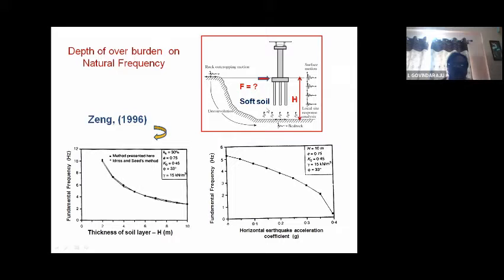It means overburden now. Sometimes you may get shallow depth, you may find bedrock, a hard stratum, a competent stratum as we say in geotechnical engineering, at very shallow depth, probably 2 meter, 4 meter, 5 meter. In some situations, you may go even beyond 30 meter. You may not get a competent strata like dense soil, but a soft soil. Now, what is the order of damage that is involved? Definitely, it is directly proportional to the depth of overburden, from the bedrock to the ground surface. So the fundamental frequency of the ground is very, very important in your soil structure interaction analysis.